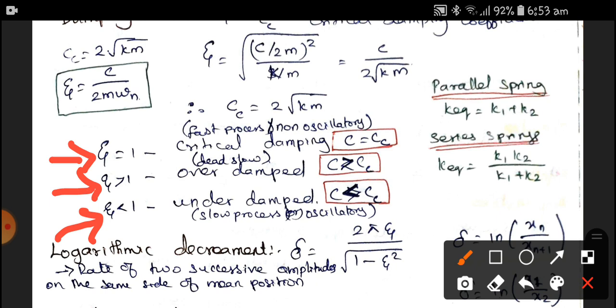If there is no critical damping, what will happen? Due to the force, the thrust of the bullet, the body will be continuously disturbed and continuously in motion. Therefore, the next bullet will not come into the picture. It is similar with a military tank launching a huge number of bullets at an enemy. The complete system should be critically damped, and only then will quick firing happen.